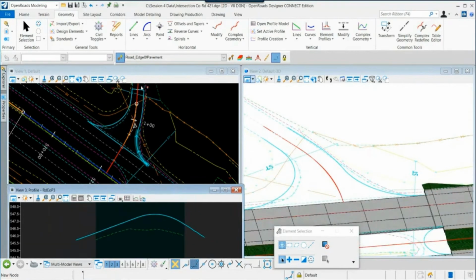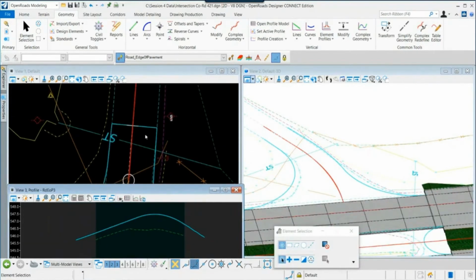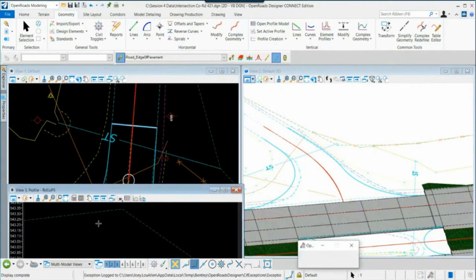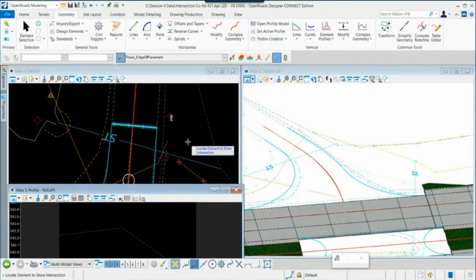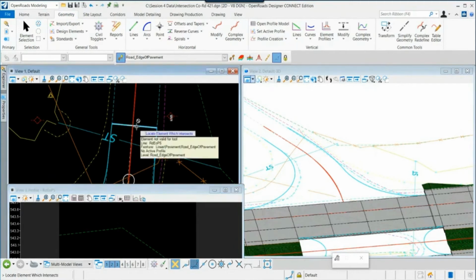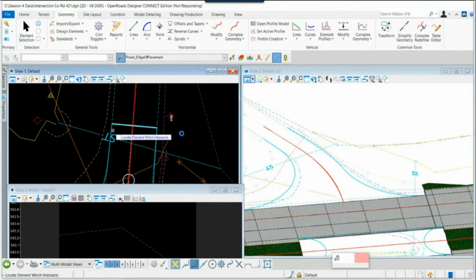Now, let's set the definition for our north and our south element. Again, we're going to profile this. Open up the profile for that. I'm going to use a command, profile intersection point, and this is a very useful command, and this allows me to see where elements intersect the profile of another element, okay? So we'll follow the prompts.